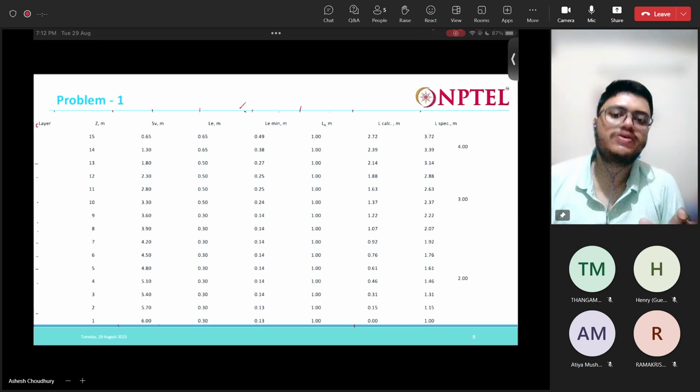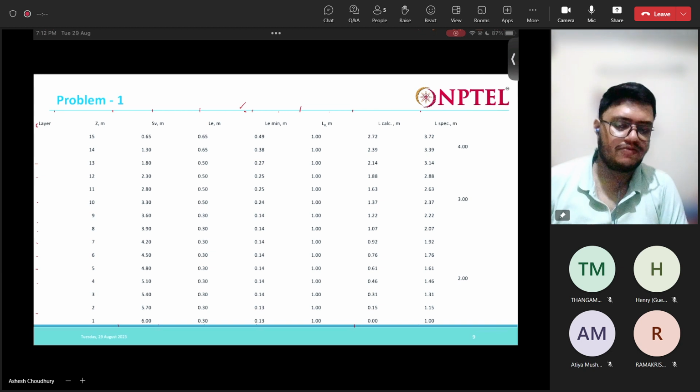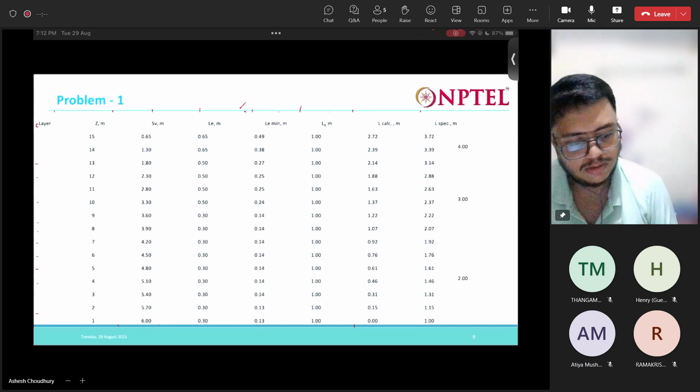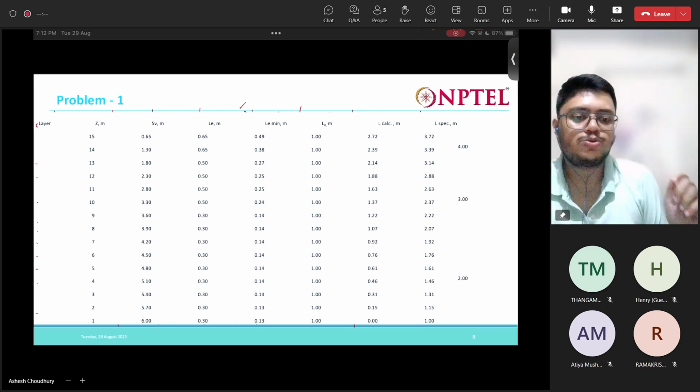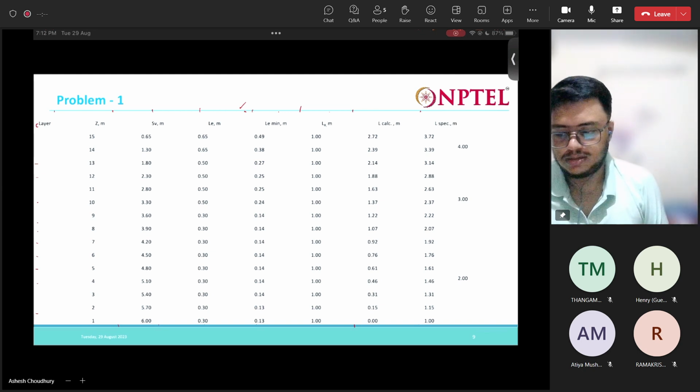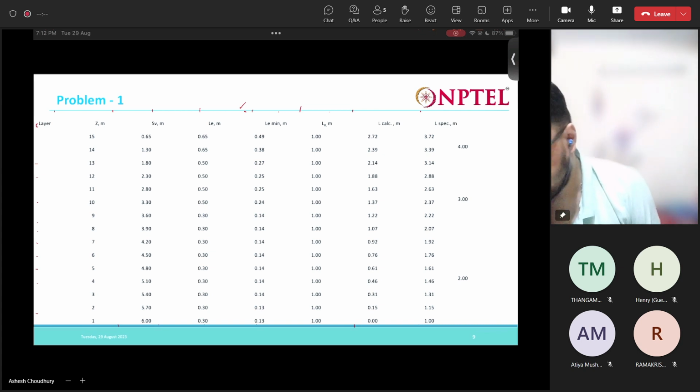That is a little bit difficult to do because we need to do it maybe using software. By doing it by hand, it's actually very difficult because we need to consider many slip circles. So we'll be just doing the first three checks, and for the fourth we will assume that it is satisfied. But in practice, we always have to do all four checks, including the slip circle check.